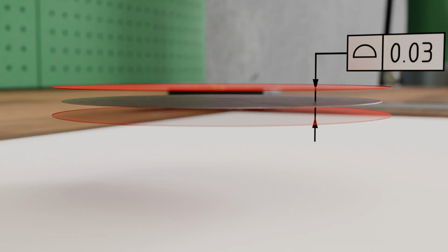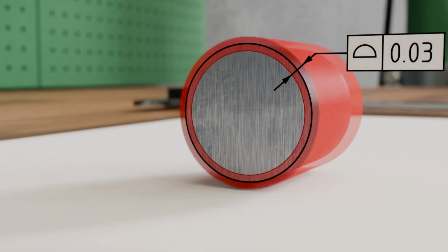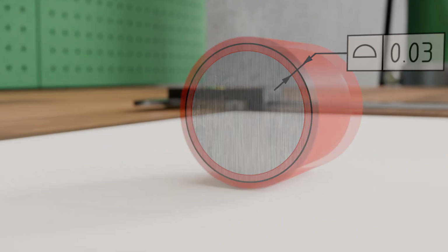Similarly, this applies to cylindricity. If we apply the surface profile tolerance to a cylindrical surface, the overlapping of infinitely many tolerance spheres results in a hollow cylinder bounded by two coaxial cylinders, whose distance from each other corresponds to the tolerance value. In this way, cylindricity can also be tolerated using the surface profile tolerance. So note, surface profile tolerance can be used not only to tolerate arbitrarily curved surfaces in their shape, but specifically also flatness and cylindricity. We have now become familiar with the 6 form tolerances and their characteristics.